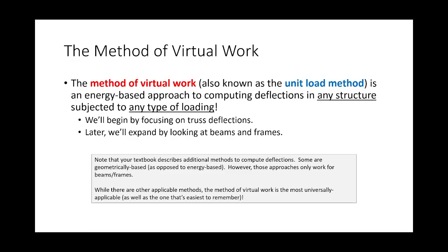Now, I'm going to summarize the latter part of that lecture again, because I think it's relevant to the example that we're about to do. Then we're going to do a full-blown, start-to-finish truss deflection example. We're actually going to compute two deflections on this truss, so there's going to be a lot of truss analyses. But we're going to break out all the tricks that we have to make this as simple as possible. What we're doing here is an energy-based method called the method of virtual work.